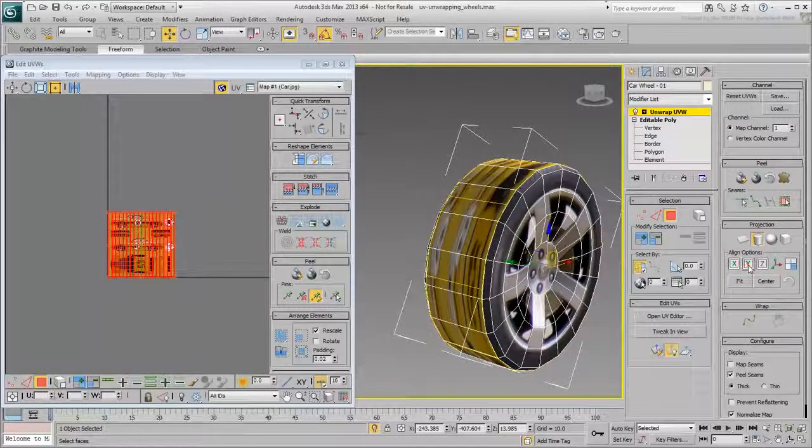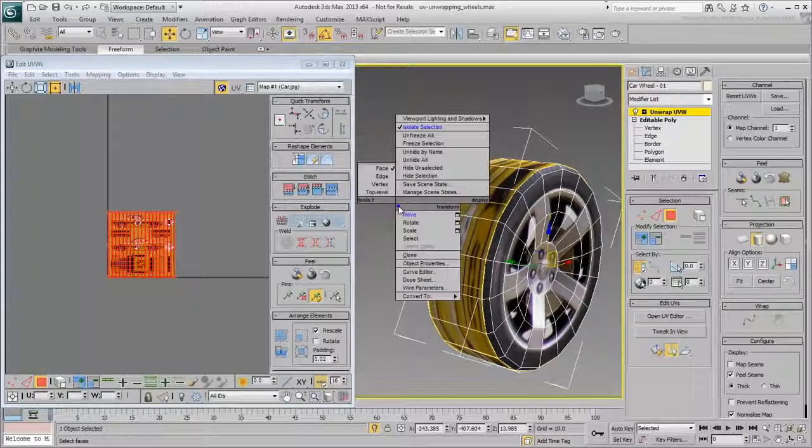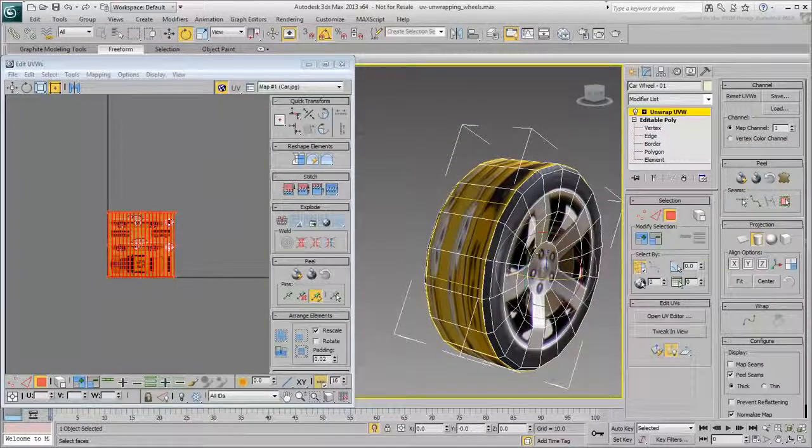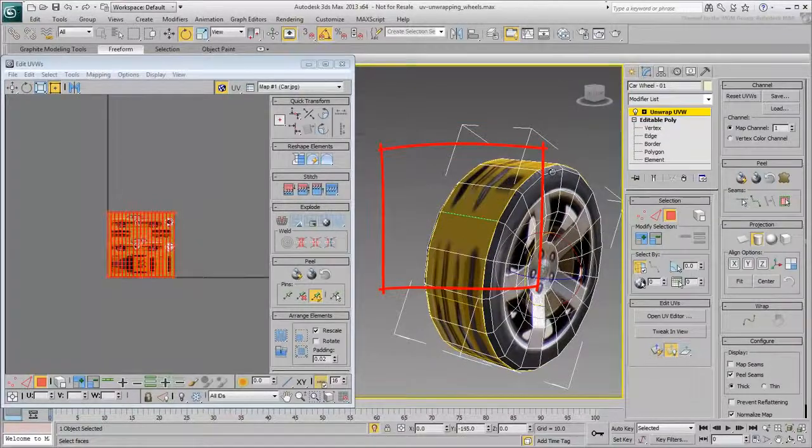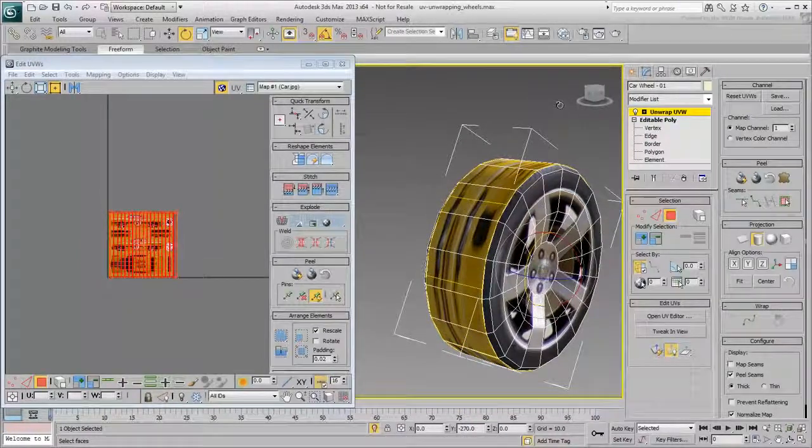Before you exit the cylindrical mapping projection, try to rotate it on the Y-axis in the viewport. Notice the green line that appears at one point. This is where the mapping seam is. By rotating the cylindrical map, you can decide where you place it.